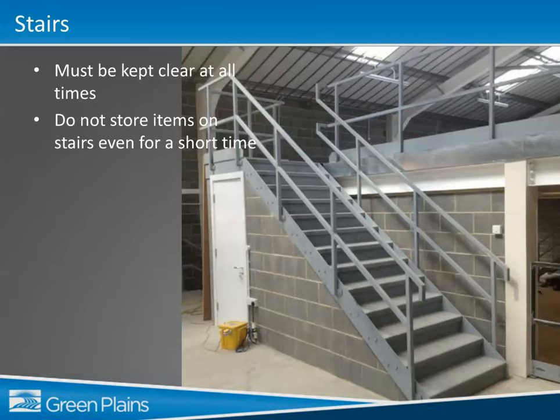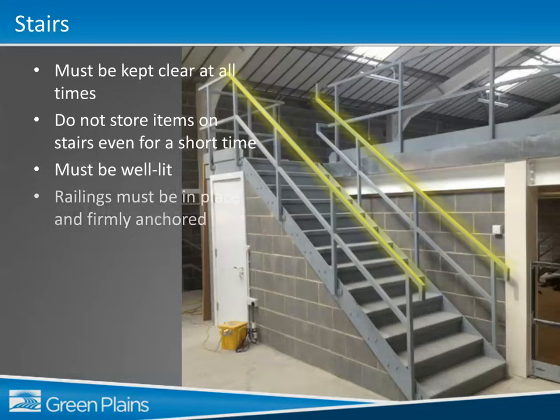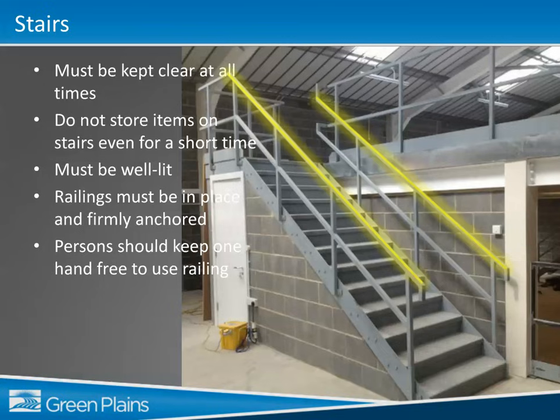Stairwells should be well lit, with sturdy handrails on both sides. Persons using the stairwell should have one hand free to be able to use the handrail. All the steps should have the same rise and depth with visible edges.